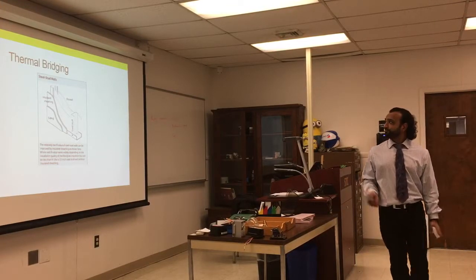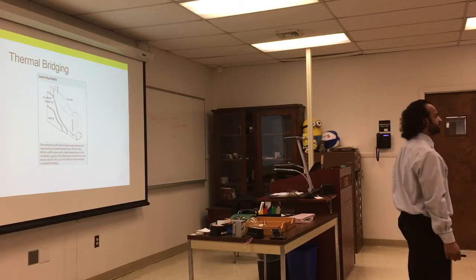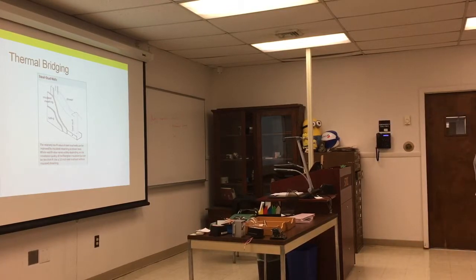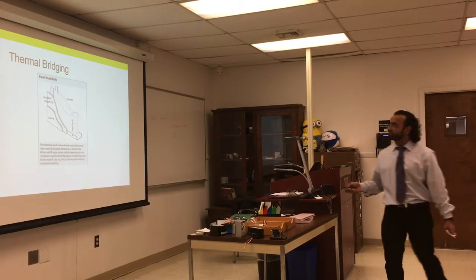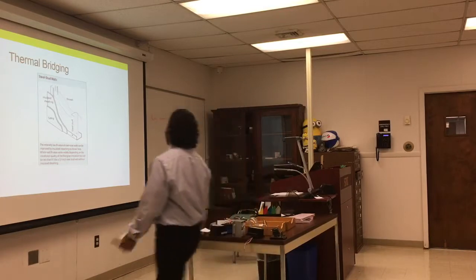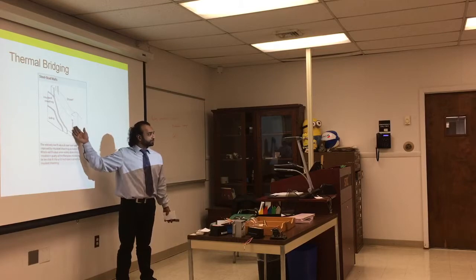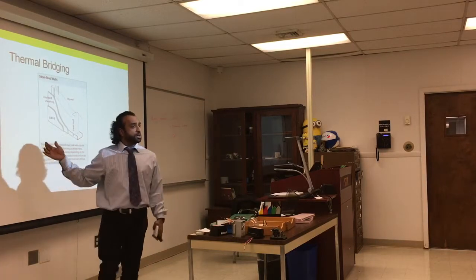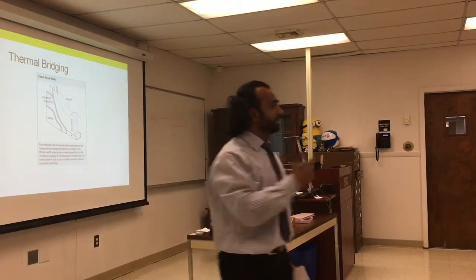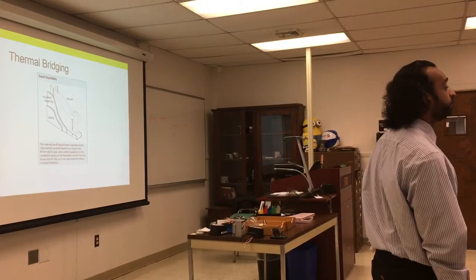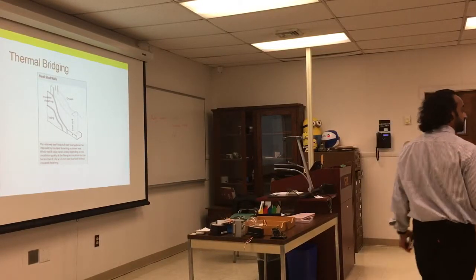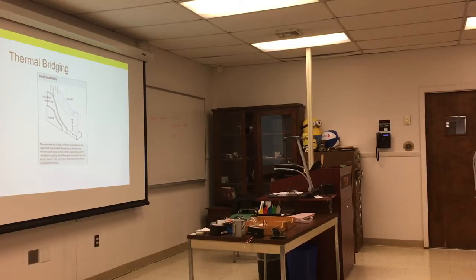Thermal bridging, what does that mean? When we look at that, we see that there are different substances in this wall. There's cavity and there are also studs. So the heat coming out of the wall will include the heat through those studs. What do you think, will the studs conduct more heat or less heat than the cavity? More heat. That's why sometimes in the winter, if the house is not very well insulated, you can see condensation happening in the wall where the studs are. Oh, they are cold, yeah.